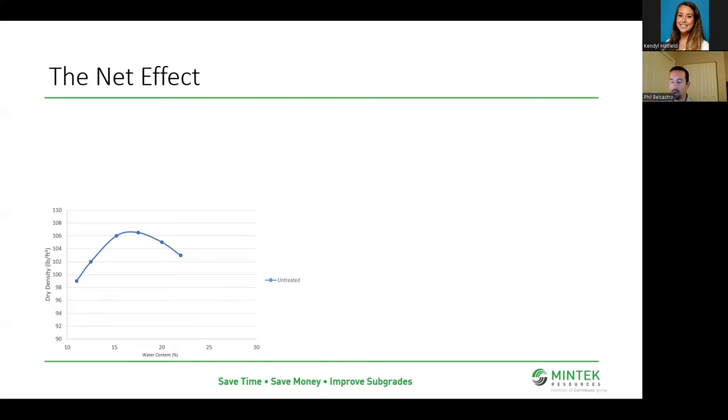We're going to build our sandcastle right there because we have just the right amount of moisture to give us prime compaction. But we're really hot now. We've got to get to the water to cool off. Way too much water under our feet now. We're slipping and sliding. That's what's happening on the far right. Way too much water in the system. So that's a quick analogy on the Proctor curve there.